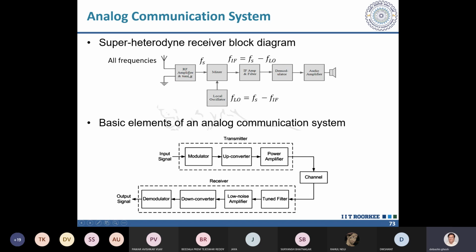This tuning circuit LC will be adjusted to that, and the local oscillator LC also will be adjusted. There are different types of local oscillators, and some of them also use LC. So suppose it is using LC. Here also the capacitance and all these things will be adjusted accordingly, so that this local oscillator produces a signal of frequency FLO equal to this.